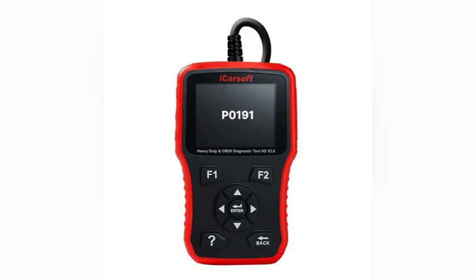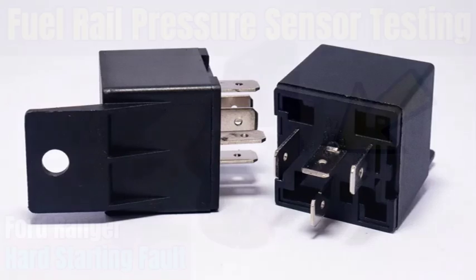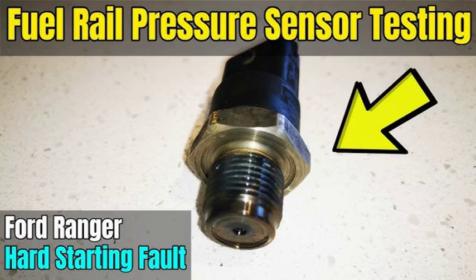If you are experiencing any of the symptoms listed above, it is important to have the P0191 code diagnosed by a qualified mechanic. The mechanic will use a scan tool to retrieve the code from the PCM. They will then use a variety of diagnostic tools and tests to determine the cause of the code. Some of the most common causes of the P0191 code include a faulty fuel rail pressure sensor. The fuel rail pressure sensor is a common failure point for the P0191 code. The sensor can fail due to a variety of reasons, including age, wear, and contamination.